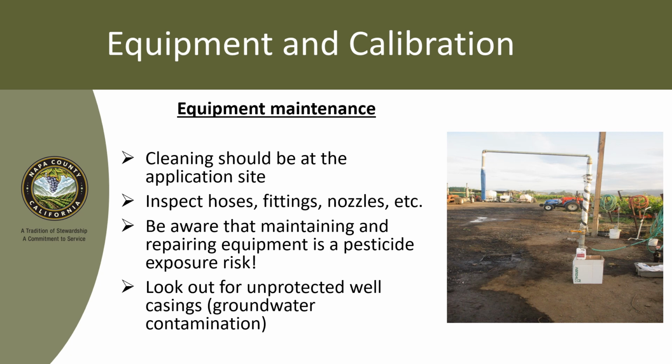So that is called an air gap, and it is a regulation that you must use some type of an air gap. And you can get pretty creative with that, but the bottom line is that you've got to have a gap there. I should mention that if you are using a closed system nurse tank, you wouldn't need that air gap. But we don't see a whole lot of that, but it is out there. So you should just know that. But the air gap is required anytime you're trying to put water into that tank from an outside source.